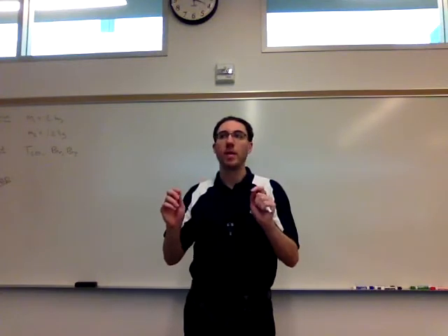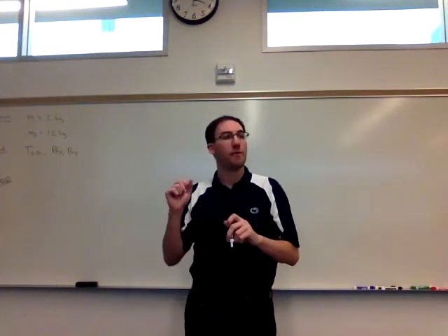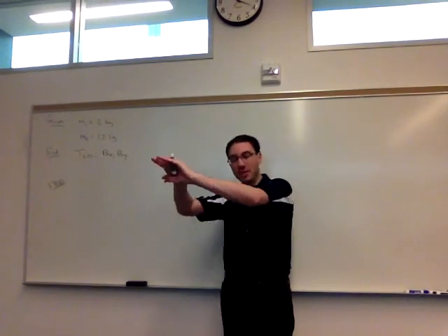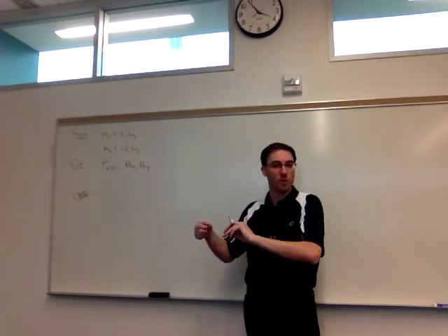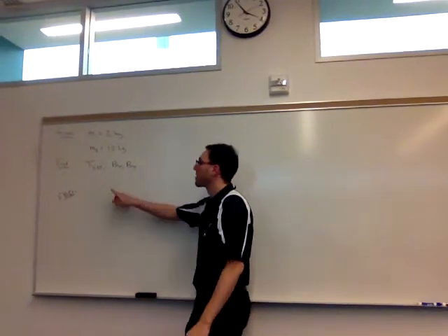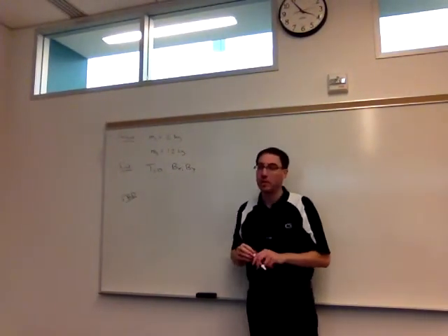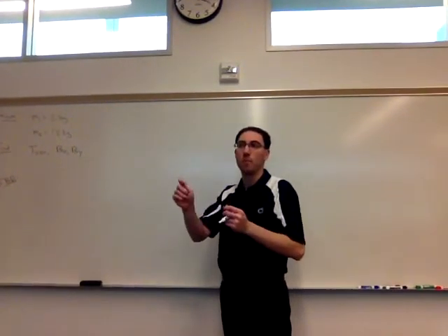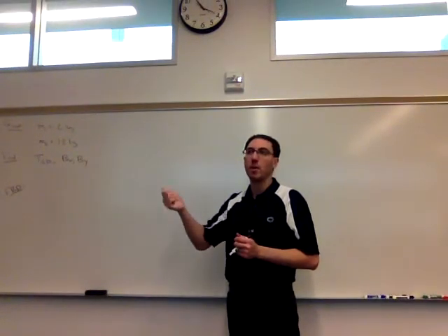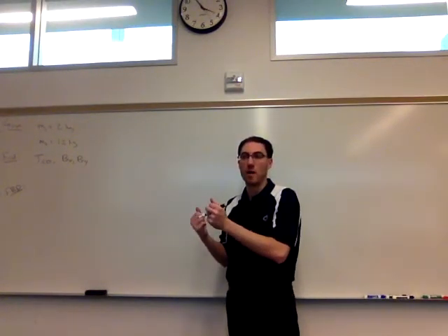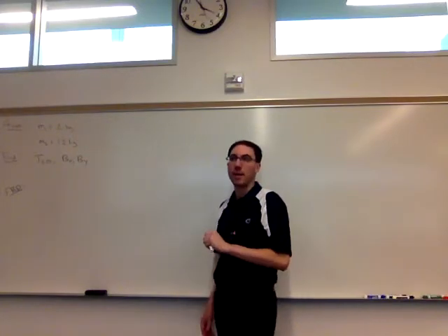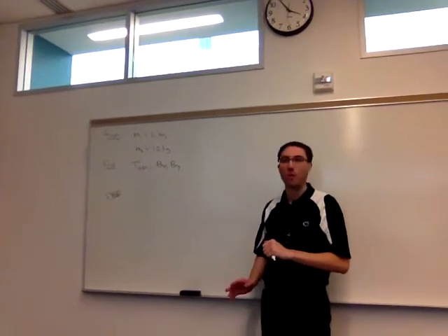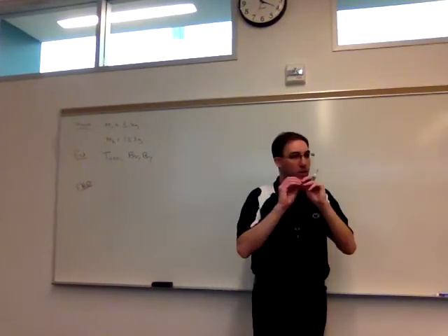Right, so if we take only the beam, get rid of the muscle, then we'll have the force that the muscle exerts on the beam. So in the structural one, just the beam, take away the force, and then we'll have the force in the rope, which is the tension in the rope, TCD. So just the beam is what we want to use as our object of interest here. If we kept the rope, then we'd have to disconnect the rope from D, which is a pin, which is going to have 2 unknowns there, which we're not even asked for what's happening at the pin at D, which would be where the muscle inserts at the shoulder. But that will be a different question. So for the free body diagram, we're going to use the beam.